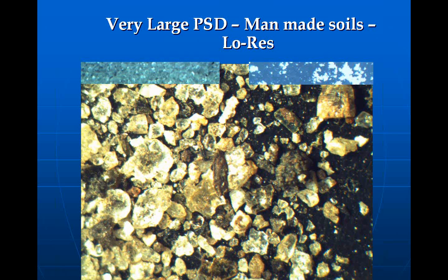Remember that on a site like this that's built, the site starts out generally by being cleared. The specifications usually call for it to be compacted to 95% or 98% of proctor, which means that the soils are packed where they will bear well. Then the building foundation is done, the footers are poured, and the building is done. There's rock put down, there's asphalt put down, islands are built. There may be a little 2-to-1 slope in or out on one side, which could be where some material is coming here, some of this angular material like what's under my cursor right now. But these sites have almost no native soils on them. And this is pretty typical.